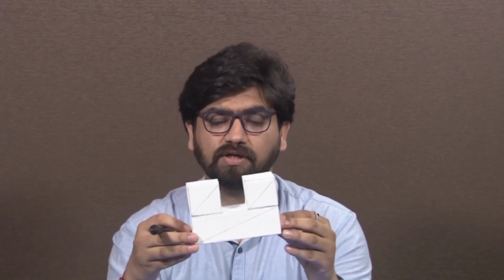Let us discuss now the support structure. If, for example, someone wants to build this part by additive manufacturing and this is the build direction, then in that case no support will be required for this particular part. However, if you change the orientation of the part, then you will realize that support will be required for some of the features.